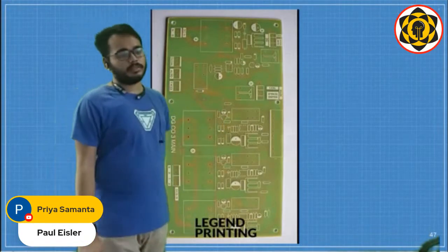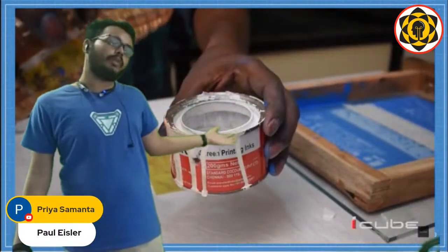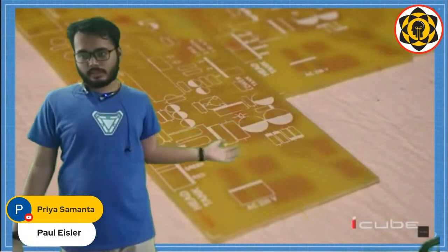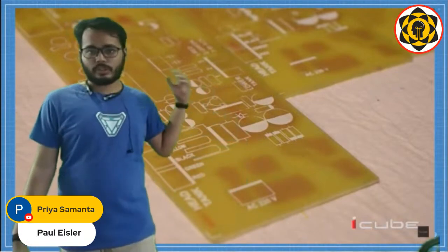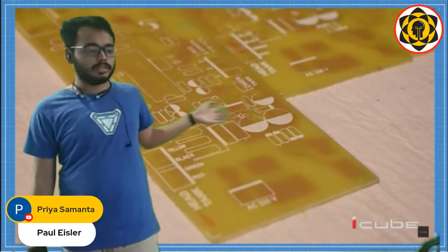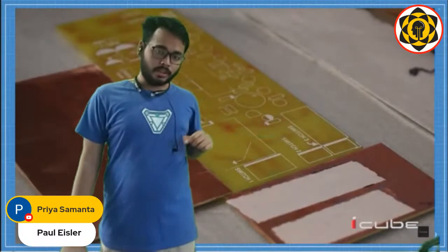Now legend printing. This is basically the part where you print the characteristics, the names and stuff on the PCB. Now this is simple white paint. Nothing else here. Simple white paint and thinner. You can use thinner or not, depending on the consistency of the paint. Up to you, up to the paint that you are using. If it's already thin enough, don't use a thinner. If it's very thick, use a thinner. So this is the legend. Same process. We put it under the screen, and we just swipe it.